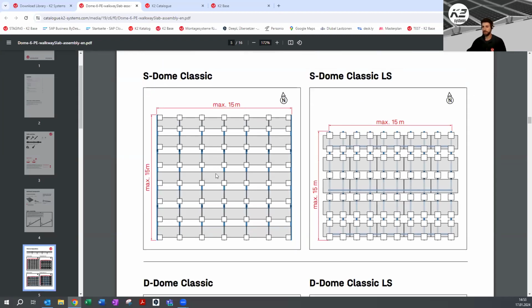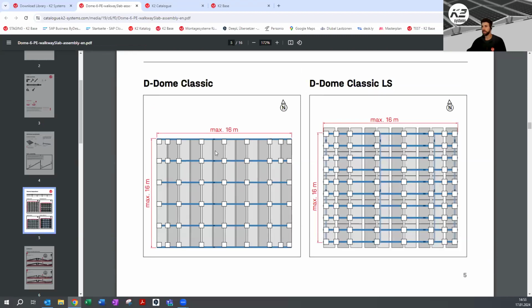For the PE plates, it's nothing. You really place only the PE plates, and if it's very necessary, if it's in a very high wind load area or on the coastal area, on the sea, lake or whatever, then you might have to add some extra ballast. But usually you can place another PE plate next to one if more ballast is needed. So you will get the report just like you can see it right now here, and we will see it later in Base.